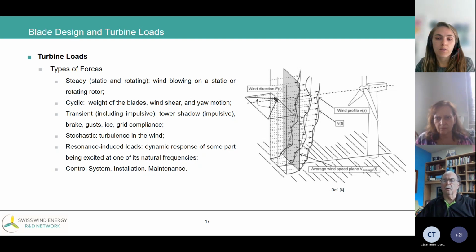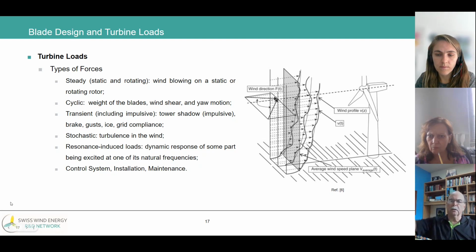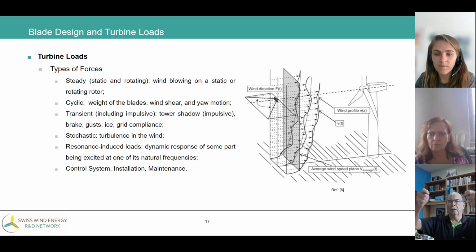I would like to make just a comment. Some years ago, I saw a presentation in Rio de Janeiro about infrared inspection of wind turbine blades. The inspection showed that there were some marks remaining from the transportation, from the place where the blade was lying on the truck. You could not see it during the inspection before mounting it, but it was there.